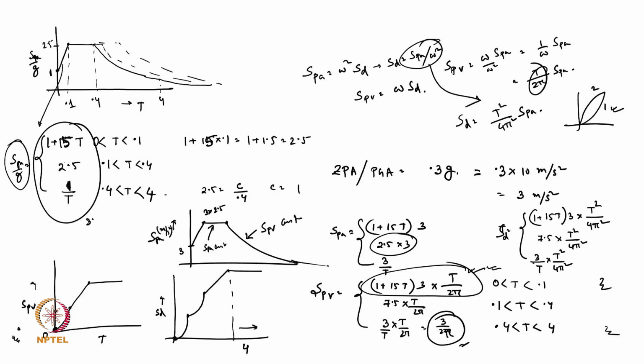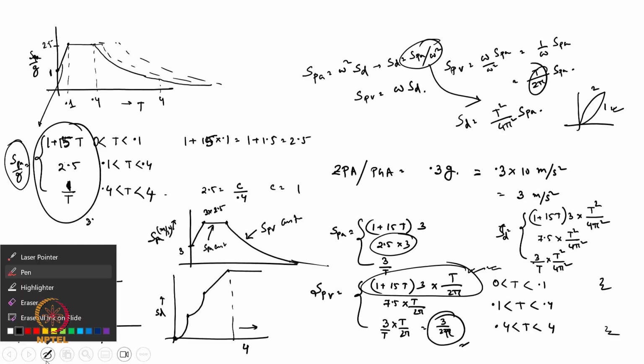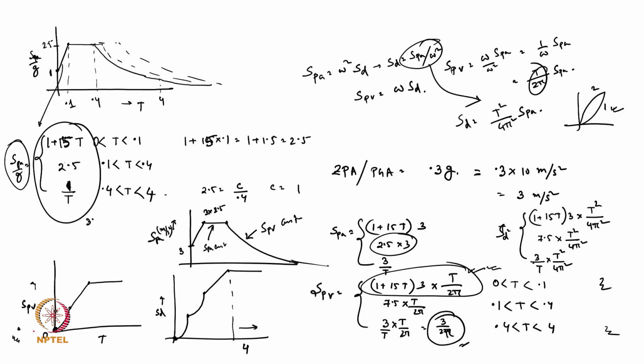Makes sense? So we generally say that, okay, in the case of a tall building, the effect of earthquake is less, because for tall buildings, if I think about our thumb rule that 1 story equals 0.1 second, a very gross thumb rule, then this point is coming from 0.1 to 0.4. That means 2-story to 4 or 5-story buildings are very much susceptible to earthquake, and they attract more forces because this is in the region of the highest value of SPA. Agreed? That is not wrong. That is a correct point actually.